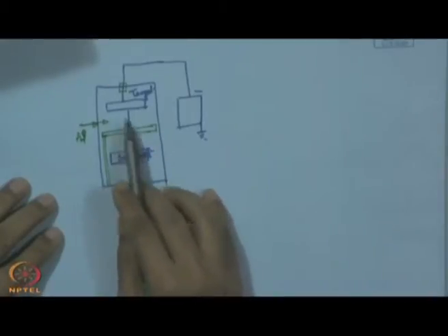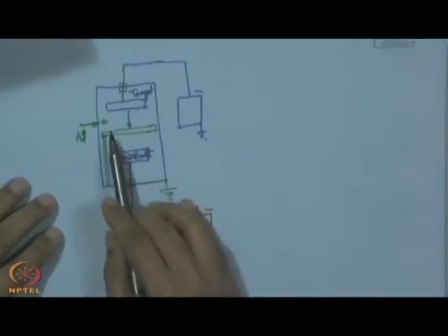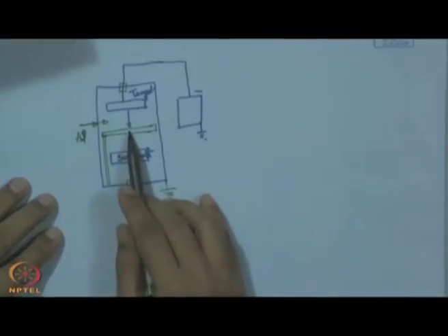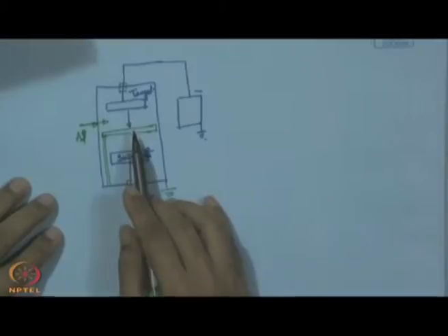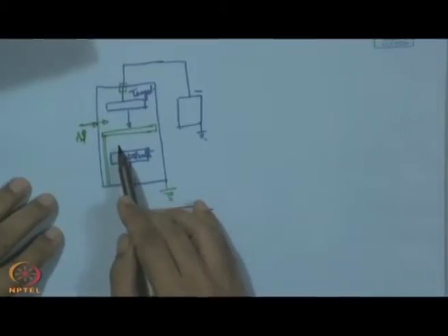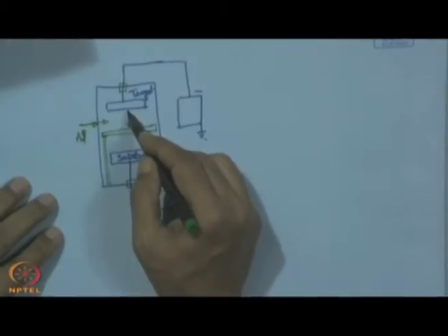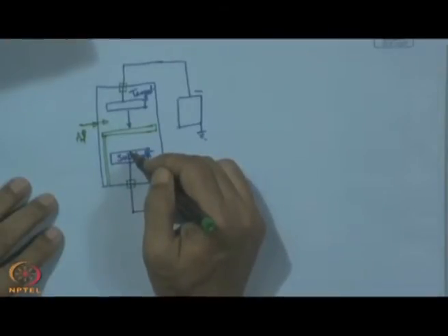Once that is done reasonably, and this is a function of the operational parameters and the time, the shutter is removed, thereby extending the plasma over this, and then the sputtering starts, and this flux is intercepted by the substrate.